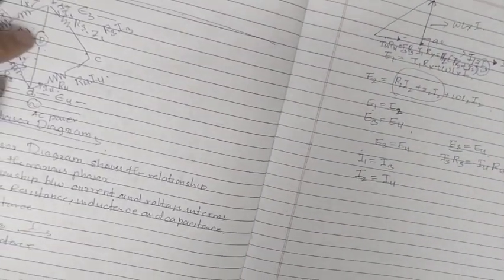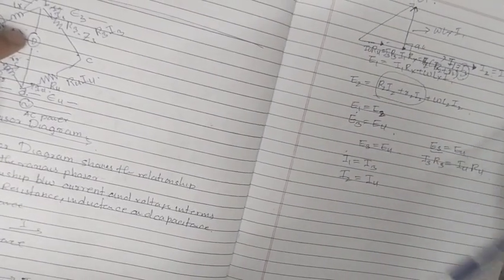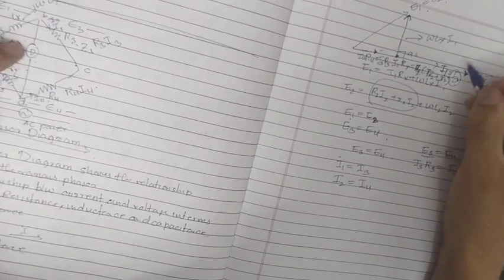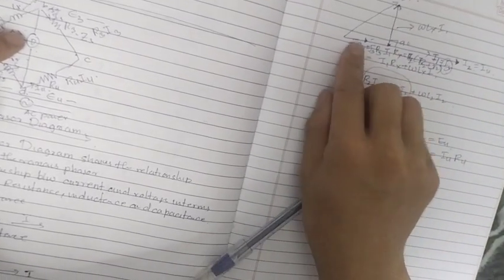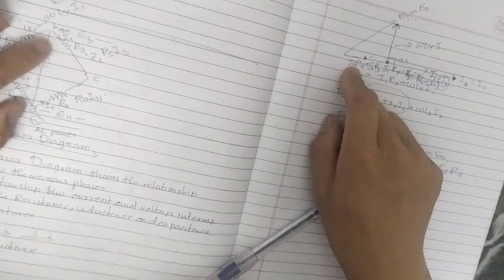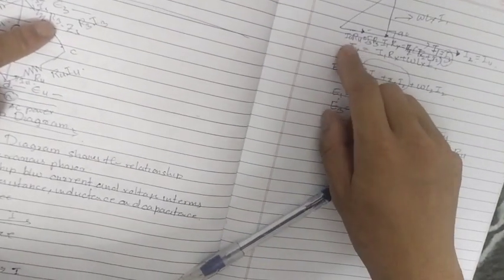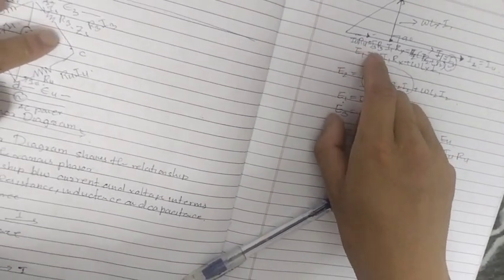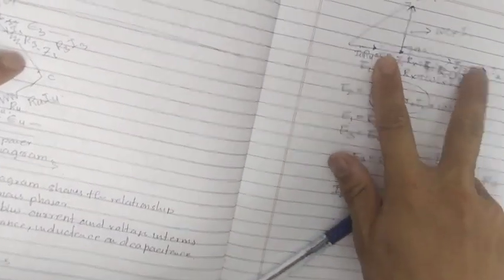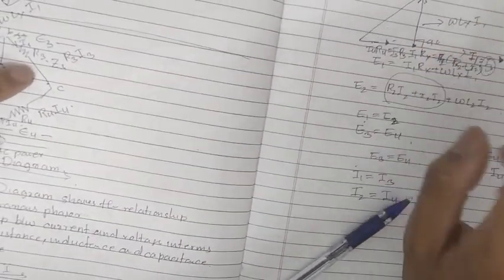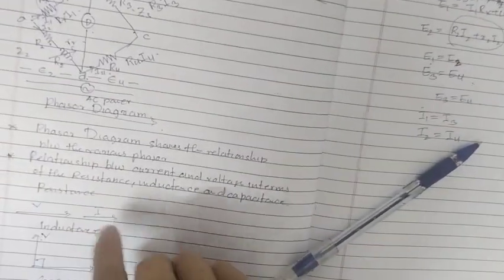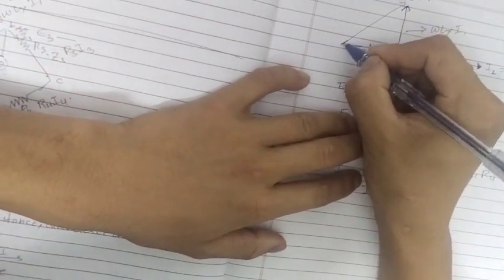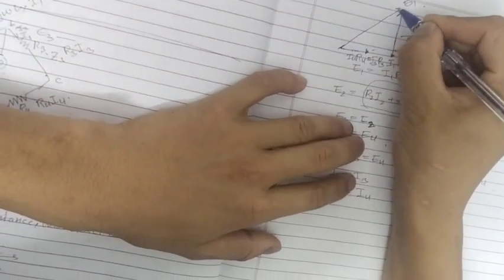That means the current I will be equal to I3. Similarly, when I1 is equal to I3, we write the voltage drop across R3 as R3 I3, so they are in phase with each other. We have fulfilled the condition for the relationship between voltage and current in the resistance part. So this is the complete phasor diagram